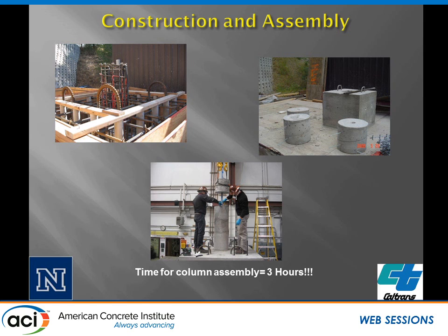So this is the construction of those columns. We went back to the single column here, or the single post-tensioning in the middle of that system. If you look over here on the left, you can see that this is the footing, and this is the reinforcement that's extending up through the footing and creating this kind of pedestal method where we can, again, exchange that out. Or you could actually make this a segment if you wanted to, but in here we're trying to investigate the reinforcement behavior. And then this is a picture of them actually constructing the specimen.